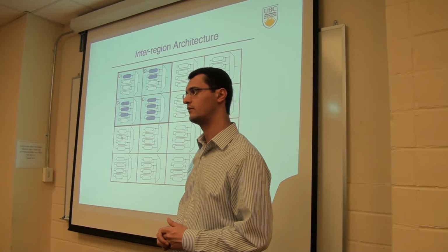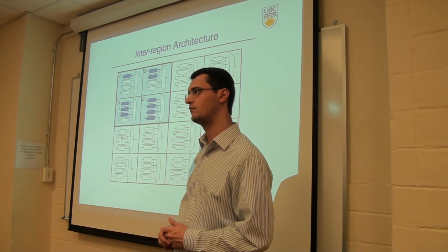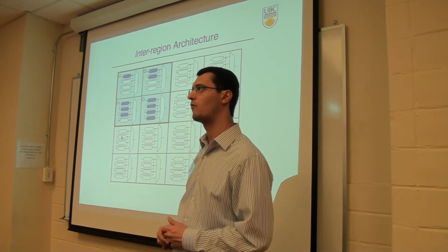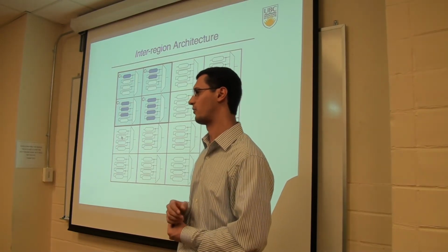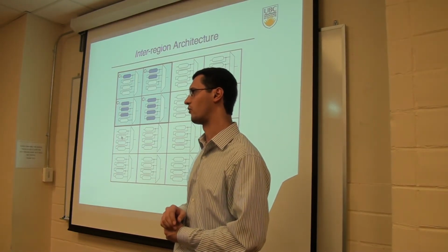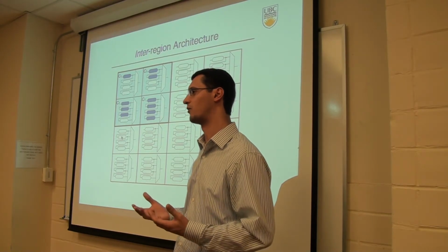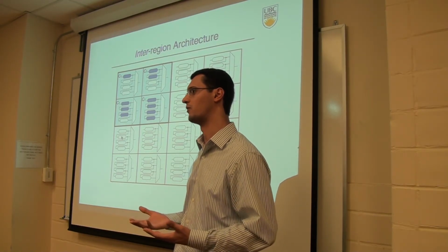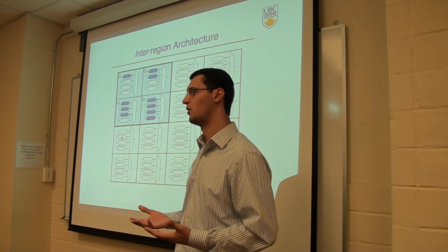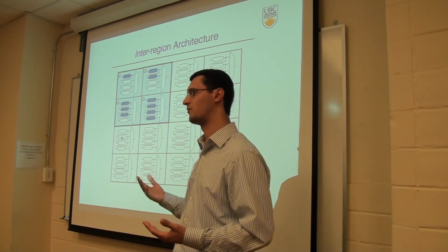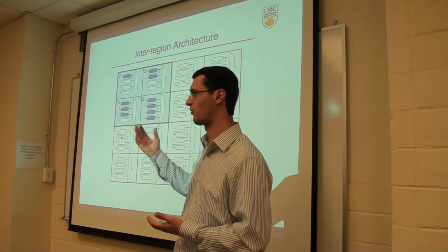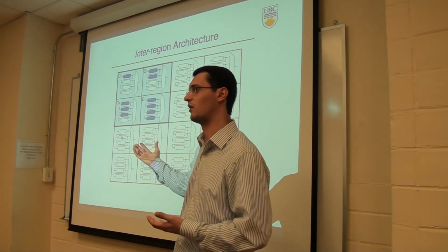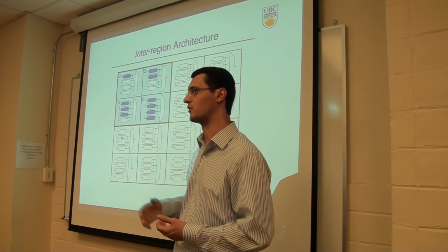What if its outputs are talking to something else that is active? Okay, so the outputs, I didn't show that in the details of the architecture, but the outputs will be pulled up or pulled down until the whole region is turned on. And there should be some handshaking signals from the controller itself that tells the other component not to listen until this whole thing is turned on.